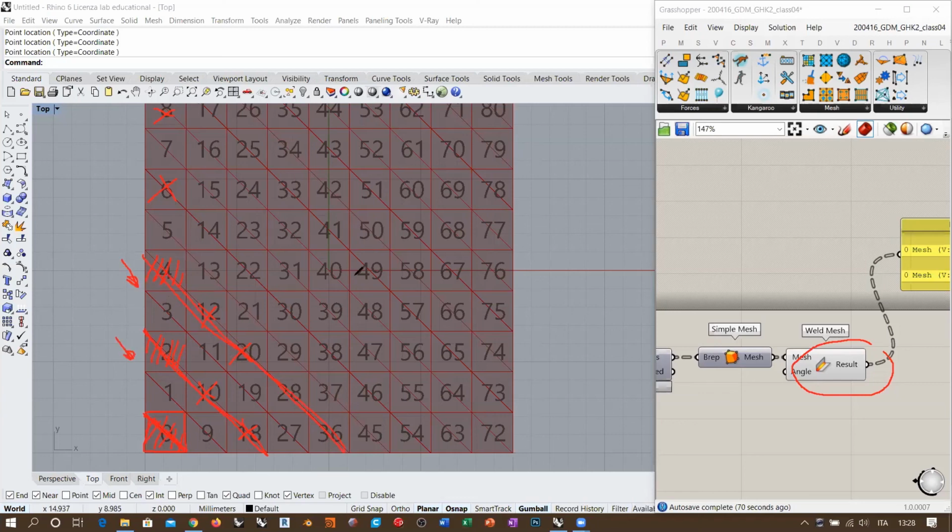And I want these other lines here to work as mountains. So in order to do this, as I am working with a regular set of polygons, which are ordered in columns, it's very easy because I need 1 polygon out of 2 in vertical. So the first thing that I do is basically dispatch all these polygons, okay, into 2 sets, and take, for example, these, which are the odd polygons, into a set, and these, which are the even polygons, into another set, okay? So once I have them, I will use them in order to divide between mountains and valleys. That's what we did in our definition.